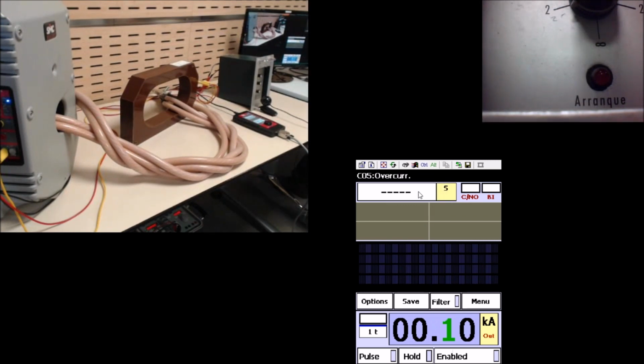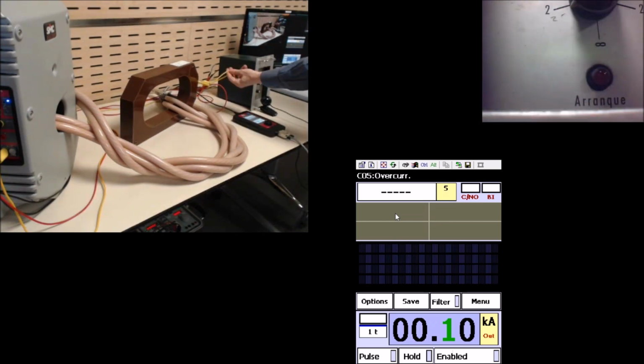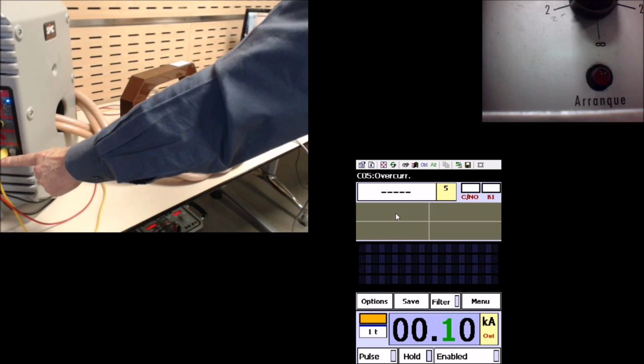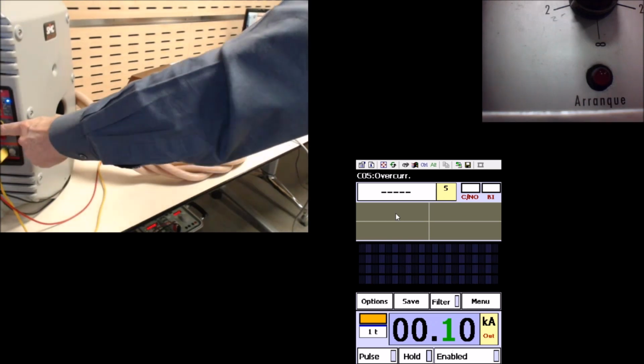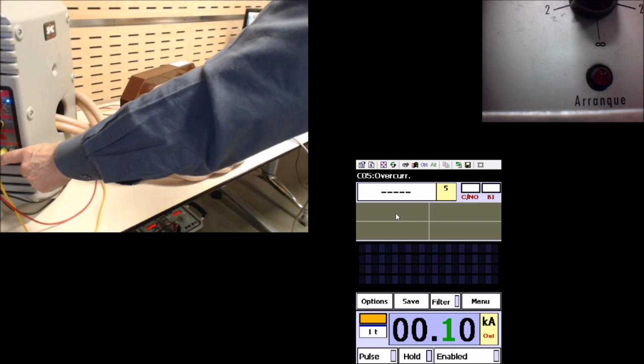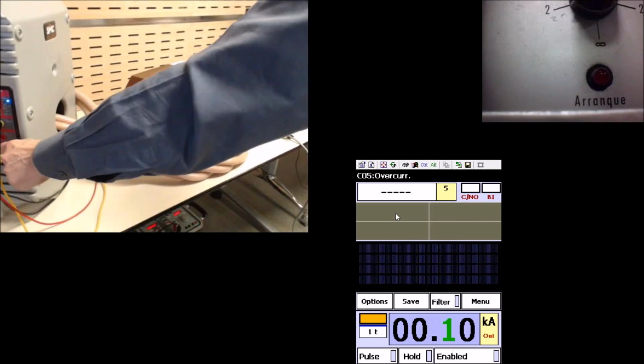There is one thing that I also want to do, which is to add an ammeter to this screen. Why should I want to add an ammeter? The Raptor has an ammeter, and I'm going to use it to display here the secondary current that is being actually injected on the relay. If you look here, you can see a yellow conductor. This yellow conductor is taking one of the legs of the secondary injection across the ammeter in the Raptor, which is here. This is the Raptor ammeter. And the binary input is here. So the relay is connected to the binary input here from the relay contact, and the current input in the relay is coming through this ammeter here.